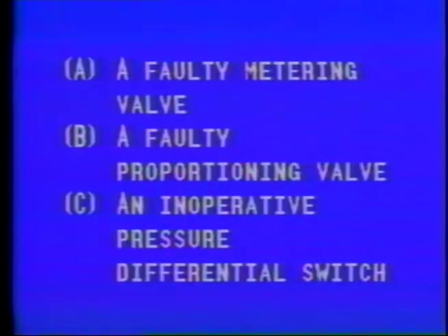The rear wheels on a vehicle with front disc brakes tend to lock up on hard stops, especially on wet roads. What could be the cause? A, a faulty metering valve, B, a faulty proportioning valve, C, an inoperative pressure differential switch, D, any of the above.